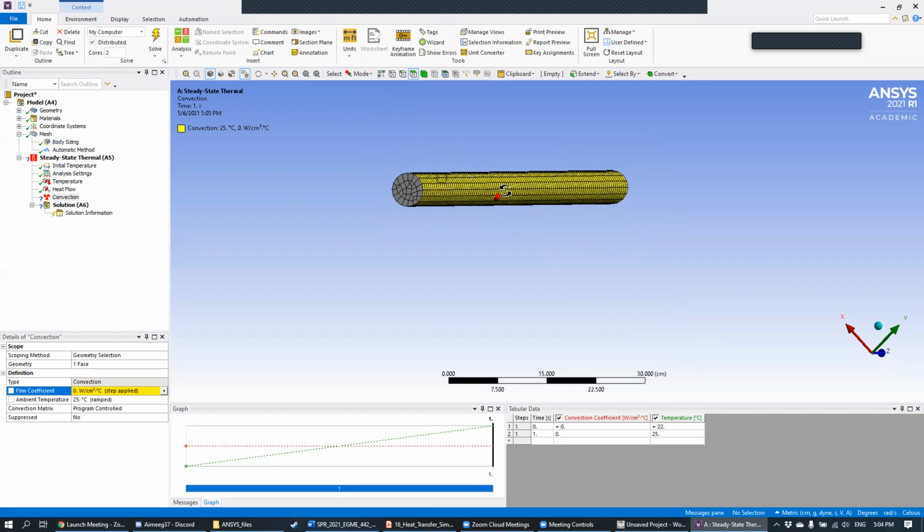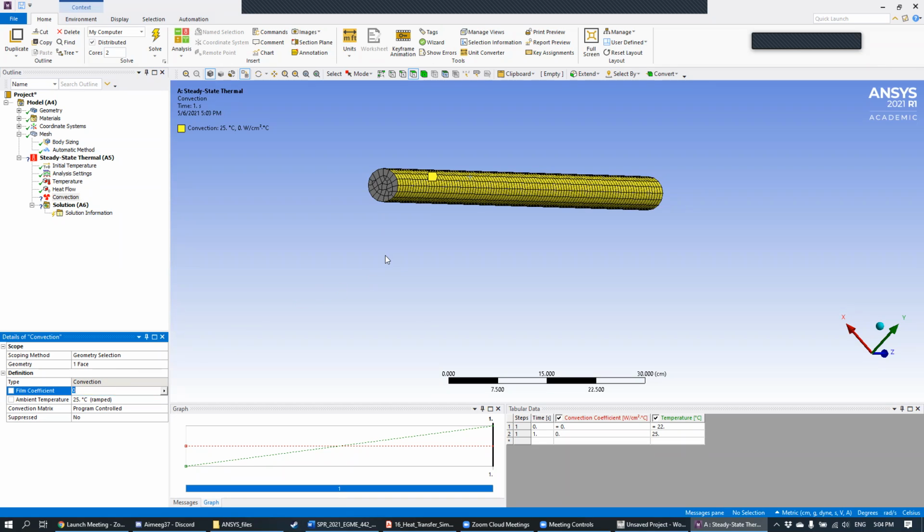And most of the time, this H, this film coefficient, is usually very difficult to estimate, right? And so you're going to need knowledge from your 407 class, or you're probably going to need knowledge from another flow simulation that you might run in Ansys, right? And so if you're running a convection boundary condition, specifying this film coefficient here is usually the most difficult part, okay? Unfortunately, we don't have time to really go over a lot of methods for doing this.